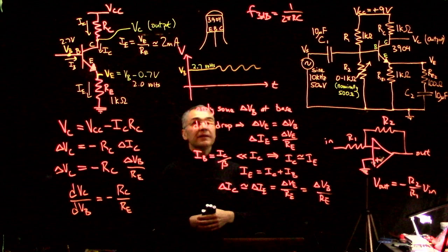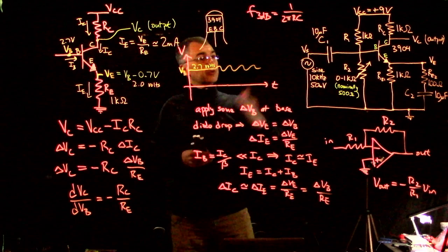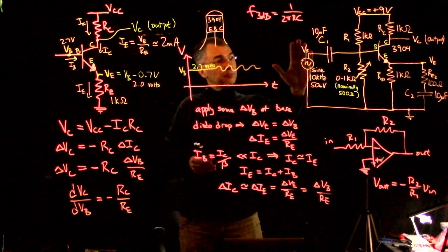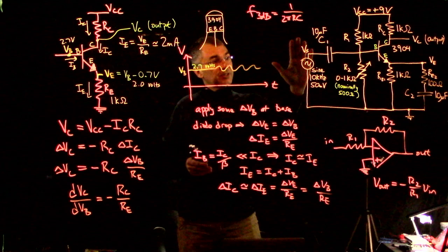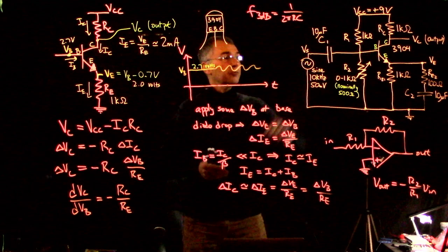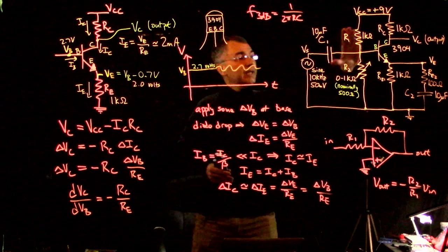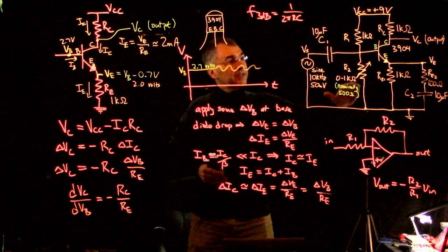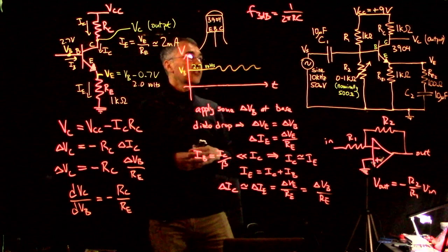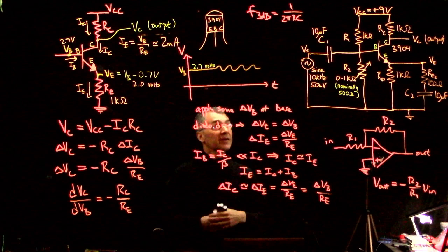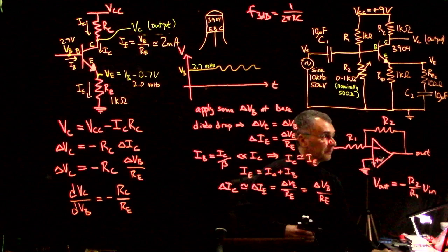And then, the purpose of this capacitor was to allow the DC phenomena here to be separate from the DC phenomena here, but the AC signal passes through. And then we have to arrange R1 and R2 so that the base is in some comfortable place. So let's erase a little bit and talk about how we decide where to put the base.